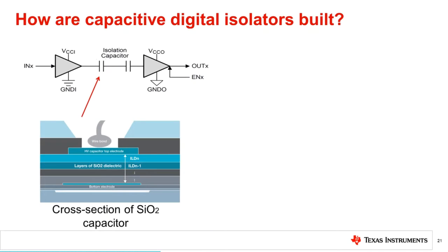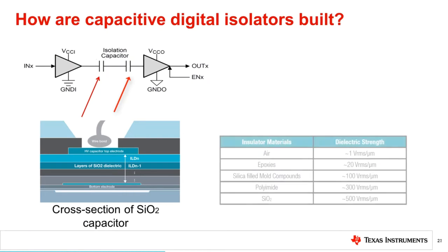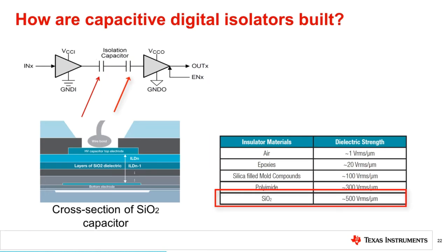The insulator of a digital isolator circuit can be either a single or double silicon dioxide capacitive barrier, which can withstand extremely high voltages by design. The capacitive-based isolator is constructed of the highest dielectric strength material in the semiconductor industry and is manufactured in a closely controlled clean room wafer fab, making part-to-part variation minimal. Because of the closely controlled manufacturing environment and the quality of the silicon dioxide dielectric, the key contributors to isolation performance are the technology itself and the design architecture.